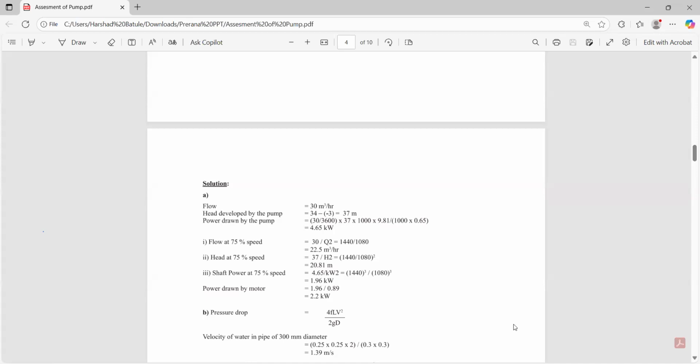Like a heat exchanger, if your heat exchanger has its own pressure drop of, let's say, 20 meters, and your piping and all this has a pressure drop of another 5 to 7 meters, your desired head should be more than 27 meters to deliver the flow rate across that particular system, because your system requirement is 27 meters. Initially the flow was 200 m cube per hour at 40 meter head, and if you are reducing that flow rate or head without consideration of any of the parameters, you can be in trouble because your flow rate cannot be delivered at the desired locations.